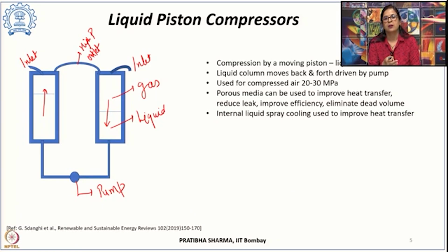At the same time, the presence of that porous media can further reduce the chances of leakage, can improve efficiency, can achieve better heat transfer, and that will also eliminate the dead volume which is there. At the same time, this heat transfer can further be improved by having an internal liquid spray cooling. Now, these droplets will not only provide high surface area for a better heat transfer, but at the same time for the liquid compressors these will finally condense back and come into the liquid.